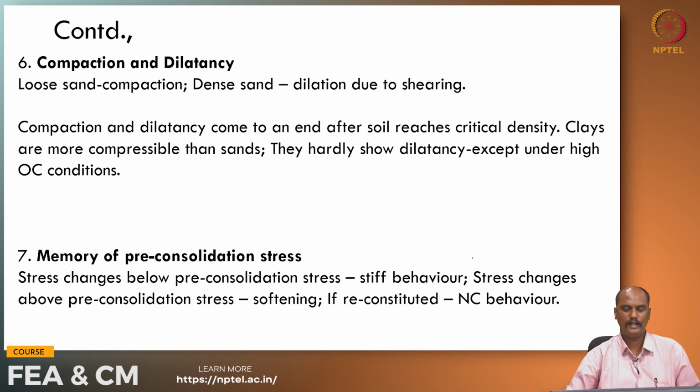And then compaction and dilatancy come to an end at a critical density or at a critical state. Clays are more compressible when compared to sands, and they hardly show dilatancy except under highly over consolidated conditions.